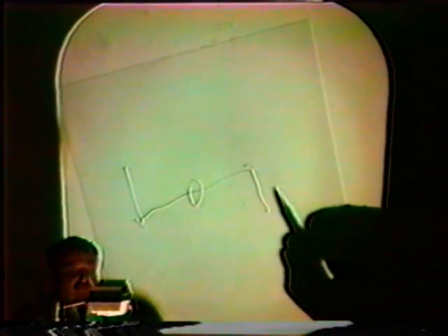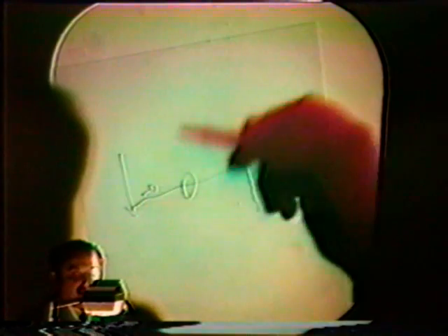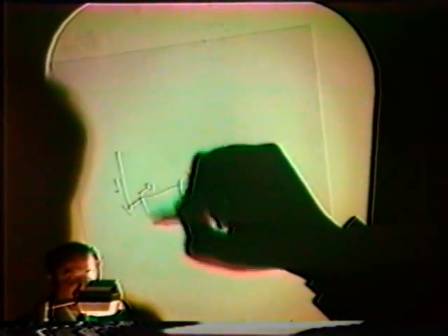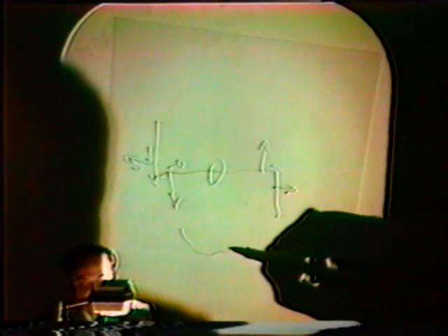Now, if you estimate the forces between the current here and the current here, you find a force like that and a force like that, and similarly a force there and a force there. Now, in a standing wave current, the currents will reverse, but 2 reversals will not alter the direction of the forces. So always you expect the pattern of the forces on the standing wave antenna to be the way that are shown there. So you expect the antenna to rotate as it is sketched now this way.